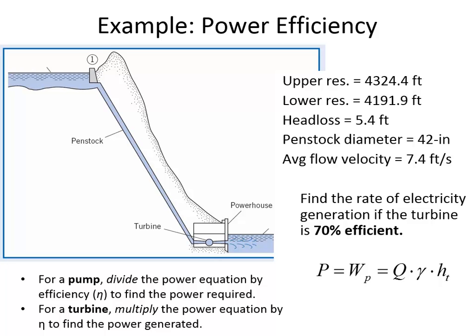What we're going to be applying is the energy equation. And last time we talked about a couple of aspects of the energy equation that I'm not going to bother to write. Remember, we talked about the difference between velocity and average velocity. Average velocity means the average velocity across some cross-section of pipe. There's going to be a whole lot of different velocities through the pipe because of turbulent flow, but we're saying the average across the cross-section. It's common for people to write the energy equation without the bar above the V. Also, I'm not going to even bother keeping track of alpha.